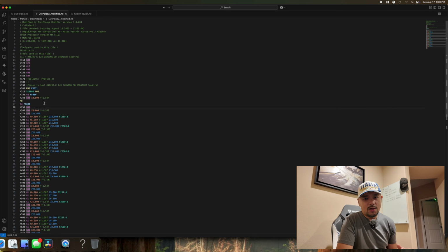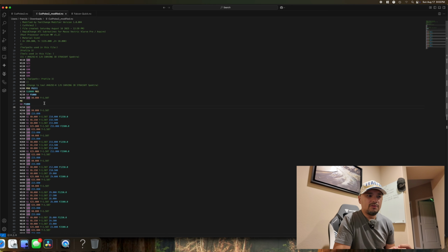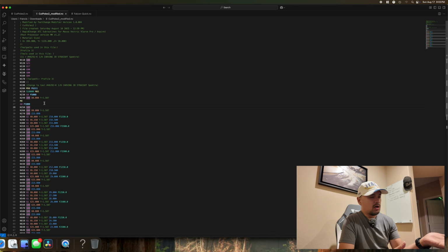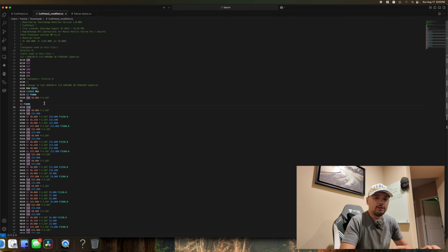By the way, this is actually a RapidChangeATC. I'm just helping out my AutoDustBoot customer with how to integrate it, because some of my customers also use different ATCs like Mosk and CATC. So I think this instruction is also applicable to not just Onefinity. I think Genmitsu also does the same thing, but instead of M98, like I said before, it's the M6 command.